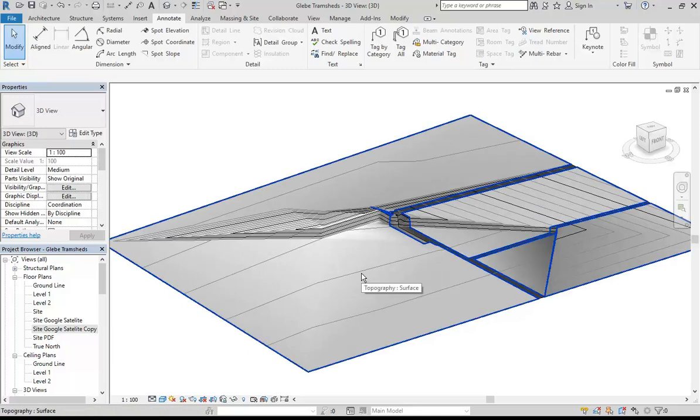So, again, I think that should give you a lot to work on. You know when you've got the ground, when you say power at the actual building? In my case, would I still do that? Yes. As much as possible, try to do it all in one file with Revit. Even though you've got options to link files together, it's not as good as AutoCAD or other programs like that. So it does work much better if you do it all in one file. It's only when you have design variations or repeated buildings that you might use links. So that should do it.